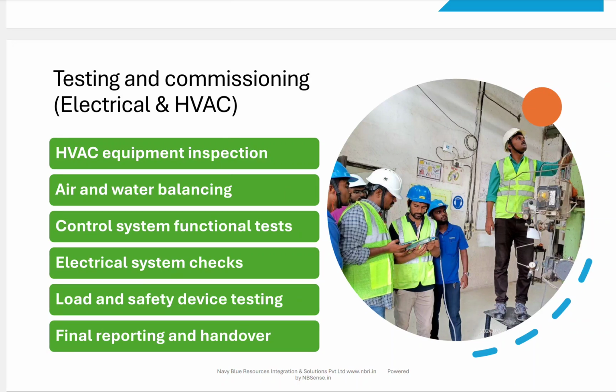Startup is not a casual approach where somebody goes and directly presses the red button. In big industries with big machinery, there is a startup protocol. Similarly, you should have a shutdown process, an SOP. You cannot directly press the red button. There is a process: which valves you need to close first, what needs to be controlled, what kind of sequencing. That needs to be followed. All this is covered under testing commissioning.